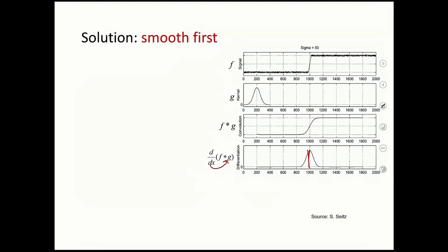If I take this differentiation, then we are discussing this. What is a derivative? The first order derivative on the edges. A difference, right? Yes, a difference. How do we find that difference? We convolve the signal or the image with a filter, right? So basically, the derivative is also a convolution operation. So it means that I have a convolution here and I have a convolution here.